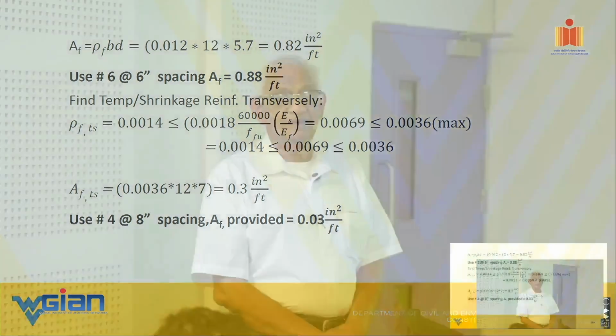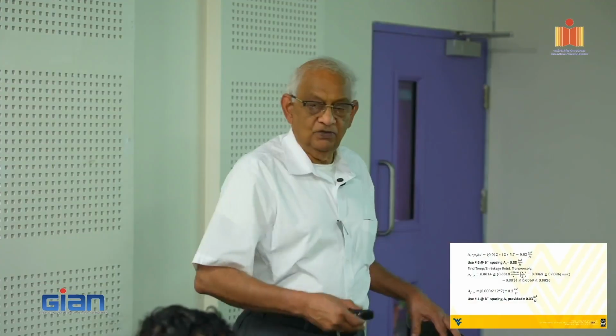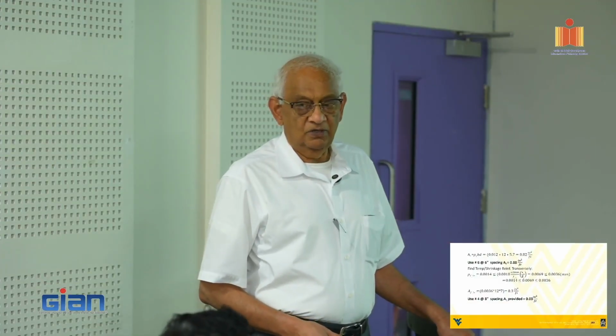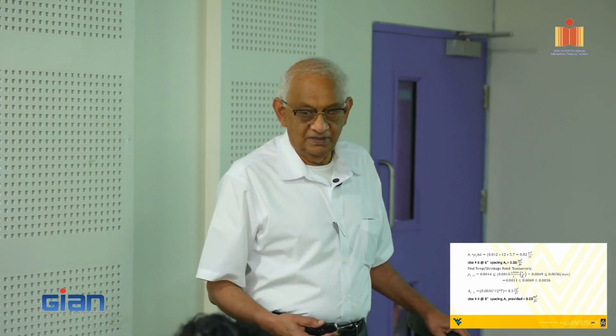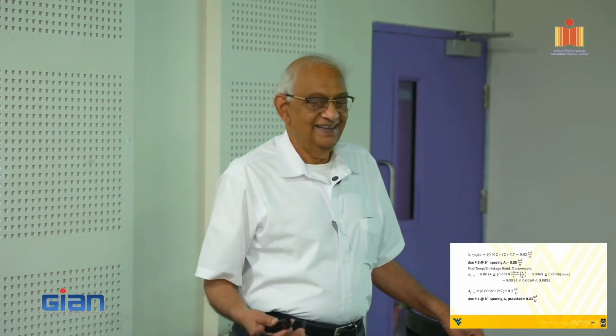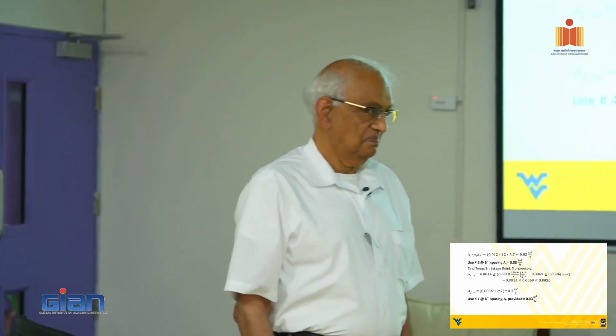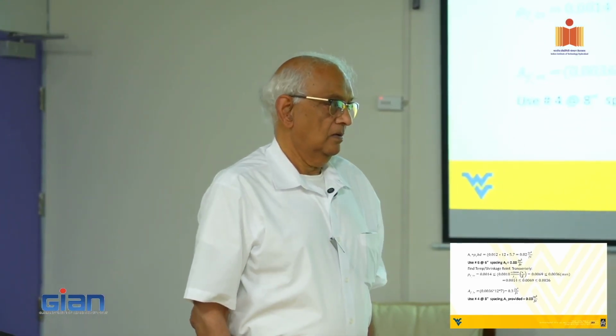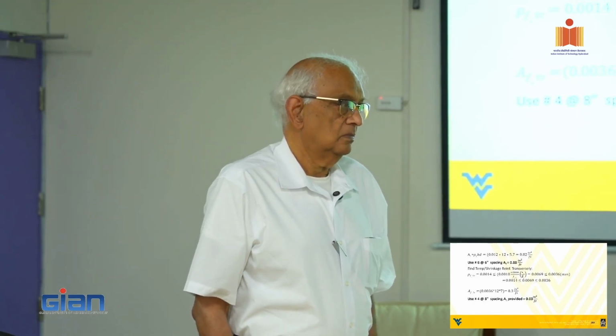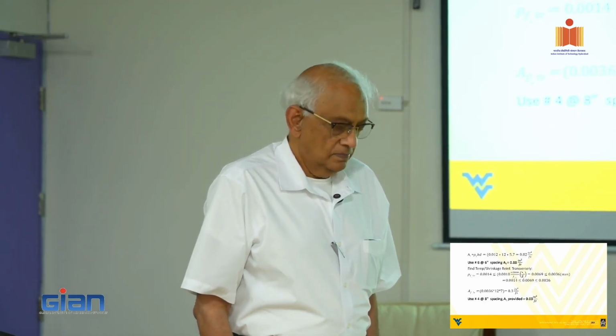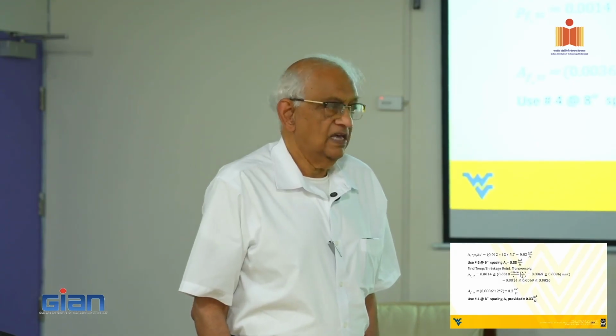In my opinion, assuming 0.0012 or 0.001 is okay, it should be lower than that because the coefficient of expansion is much lower in FRP than in steel. Actually, most of this shrinkage problem we are finding is, yes, temperature effects are less. Mostly, at least in the Indian context, they use a higher water cement ratio. That tends to be the major shrinkage issue. That's right. More fibers.